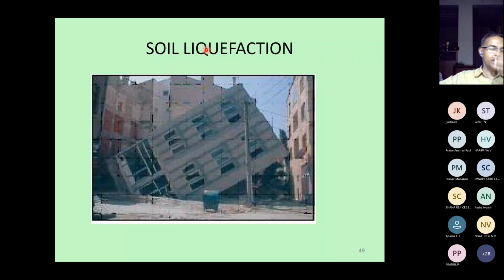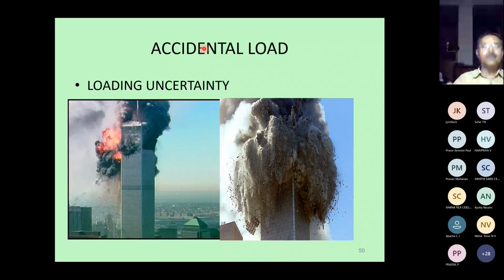And this happens for such soils where our N value is less than 10, or very loose condition, and the soil is saturated sandy soil. For clay soils, this will not happen.